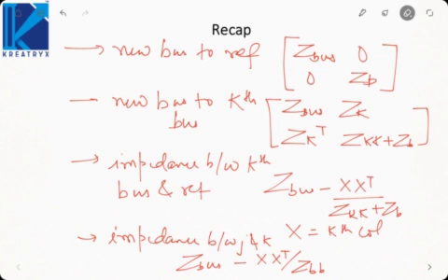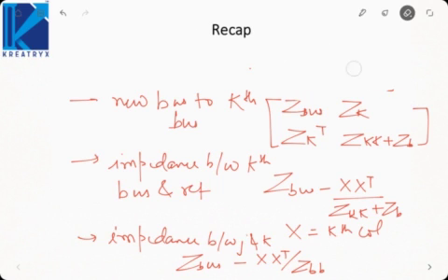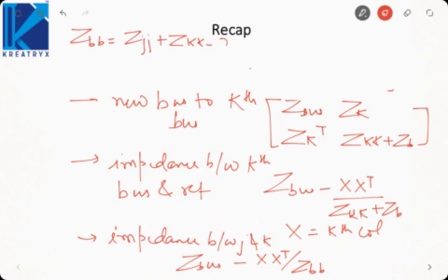Now here Zbb was equal to Zjj plus Zkk minus 2Zjk plus Zb. X was equal to jth column minus kth column. Okay, so this is what we looked at in the last lecture, and we saw that to remove any transmission line between the two buses, we will connect the negative of the same transmission line between the same buses. Okay, so that is the method of removal.